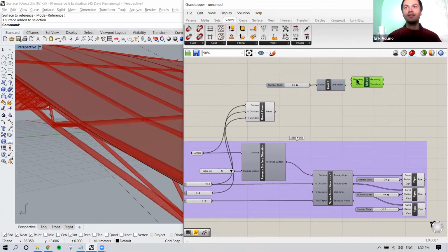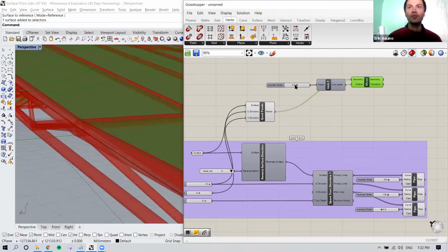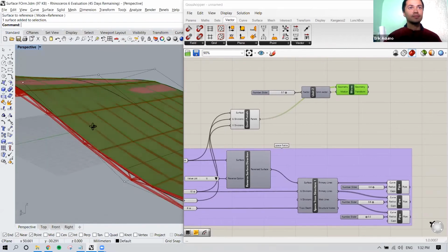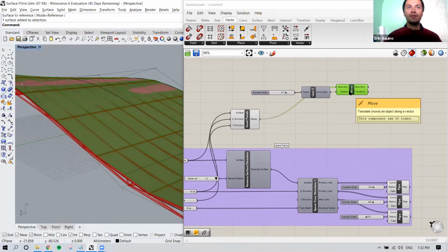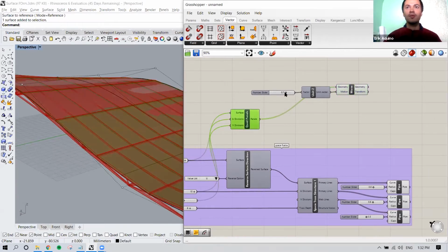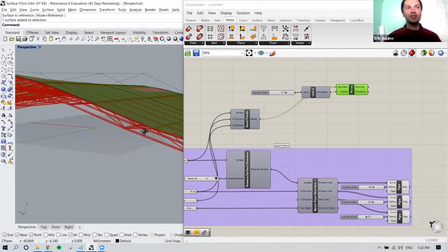We can connect these. And then lastly, our geometry to the panels. And I'll probably want a little more in this case. And now that we've moved it, we've created a copy essentially of these quad panels, 0.7 units in the Z direction, and I won't need this initial component. So I can right click it and unpreview it, and now we have just the geometry that we want.